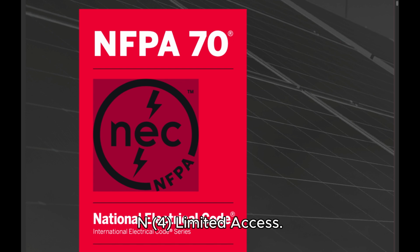(4) Limited access. Where equipment operating at 1000 volts, nominal, or less to ground and likely to require examination, adjustment, servicing, or maintenance while energized is required by installation instructions or function to be located in a space with limited access, all of the following shall apply.